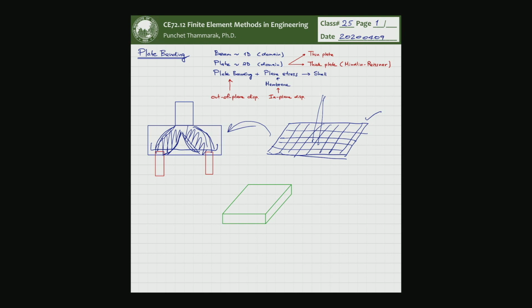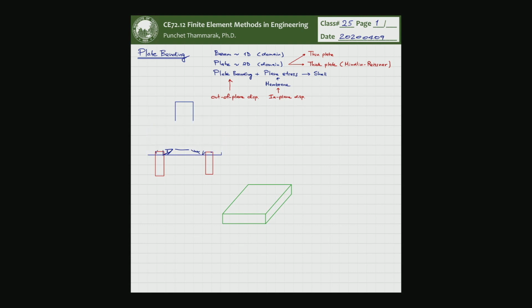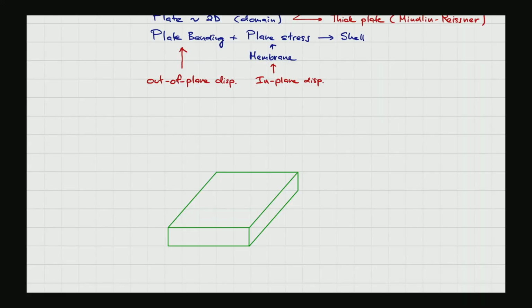But sometimes if you really want to check what's going on in the foundation, especially when dealing with a very important case, you might need to come back to finite element analysis with continuum elements in order to get the actual load transfer mechanism in your foundation, in your pile cap or thick element.